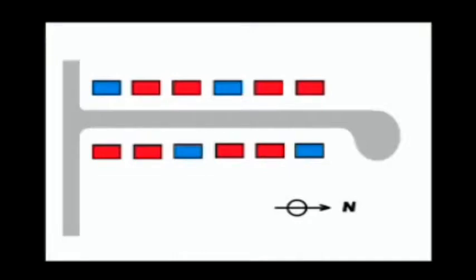These crawl spaces were converted to closed crawl spaces for the field study. We did this by carefully air sealing the exterior walls of the crawl space. In this shot, you can see workers using rigid pink foam board to seal off the foundation vents, as well as the wall hole for the duct connection to the outdoor packaged unit.